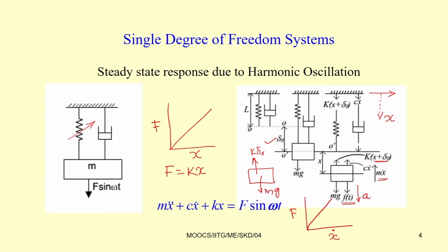Now, by writing the equation of motion, we can write all of them in vector form. Let us put a unit vector along this direction. We can write the total force acting on the system as m x double dot plus Ft. We are taking positive i in this direction, so i minus k(x plus delta 0), C x dot, m x double dot. All these are in the opposite direction, so we put minus i, and this will be equal to 0.